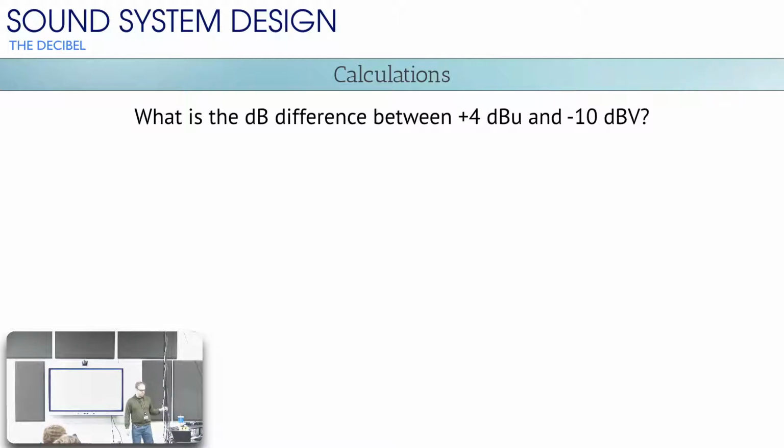You get a question? Why do they have a different voltage for consumer and professional grade? It's not like a big difference. So some of it has to do with balanced signals, because that's a big difference between consumer level stuff and professional level stuff. In the professional world we like to use balanced signals because we're running our cables a lot longer distances. In your living room, your cable's a couple of feet between devices, and that's not enough distance to really pick up a lot of noise or interference on that cable.